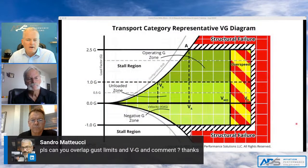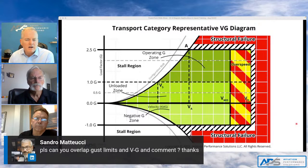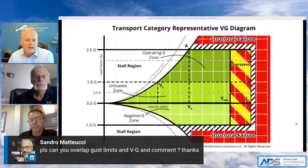I'm going to pull up a diagram here that I don't know if it's going to help. Dave, this question is a good one, talking about gust limits, probably referencing maneuvering limitations in relation to maneuvering speed, because gust limits have a different trajectory. Even though it's not marked on here, this diagram actually shows the changing upper limits in a configuration going from 2.5 down to 2. It shows the shape change of that upper shift and lower shift. But Dave, do you want to talk about where the gust limits overlap and how they might be represented on a VG diagram, if at all?